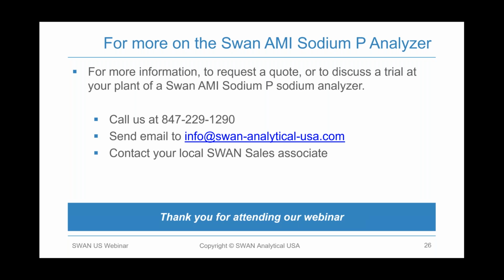Cycle time will be dependent upon the flow, but it's going to be approximately 3 minutes or so. And the maximum number of sample lines for our analyzer, I can't speak for competitors, is 6 sample streams with our external sequencer. We also have an option for the single line analyzer. You can add the dual stream option, in which you can monitor 2 different sample streams with the one analyzer, depending on your needs.